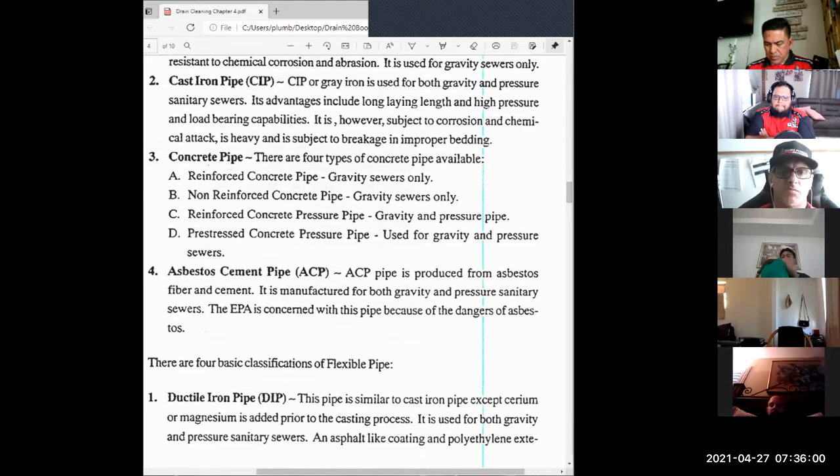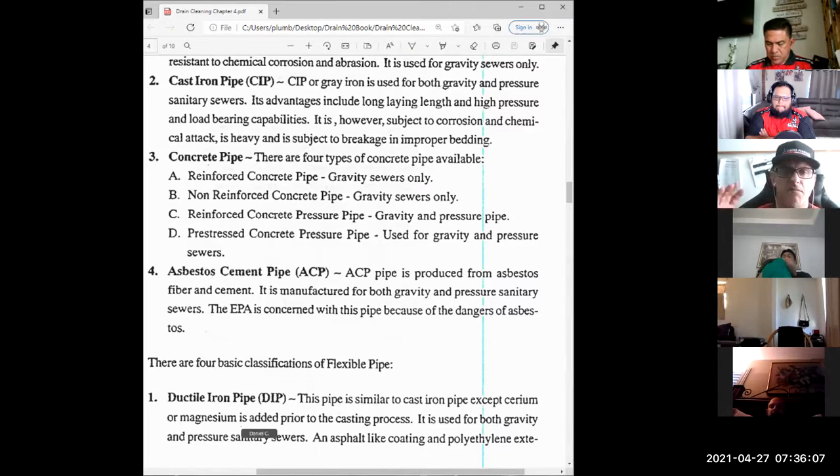You're not going to find asbestos under the slab. You'll find cast iron 2 feet outside of the foundation, and the main will be what is asbestos. You'll never find asbestos tie-ins and fittings underneath a cement slab. So you could cut into the cast iron, shoot through the cast iron, dealing with the asbestos and leaving it intact in place, because a lot of times that asbestos pipe is still actually in really good shape.